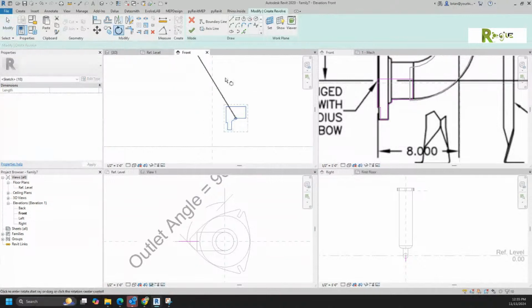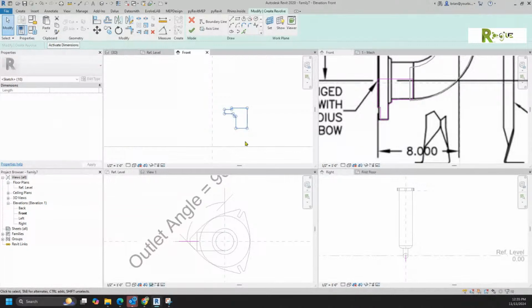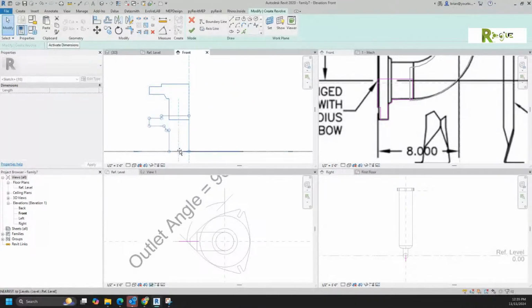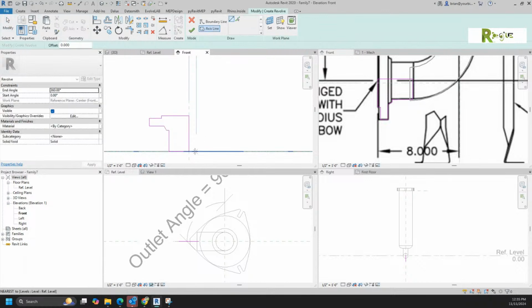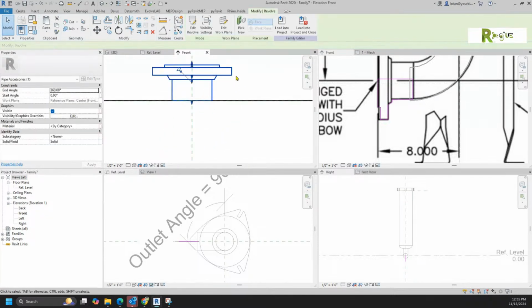So then I just rotate this as I need it. I will tell you that rotate will get off. Now here, do you move? If you were going to try to get this back over here, would you do a move and snap to there? What Revit really wants you to do is grab this line. That's going to cause you to go in that alignment. Grab this line. That's going to cause you to go in that alignment. And now you're where you need to be. Does that make sense? Yep. We put in our axis line. We finish. We've got one.